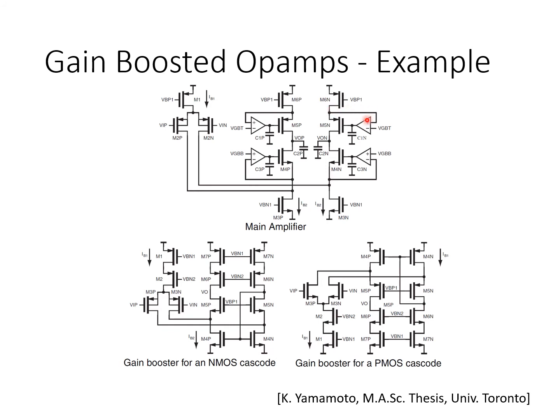So therefore, these two amplifiers have to have NMOS input pairs, whereas the gain boosting amplifiers driving the NMOS Cascode transistors accept as their inputs relatively low voltages. So these two require a PMOS input stage.